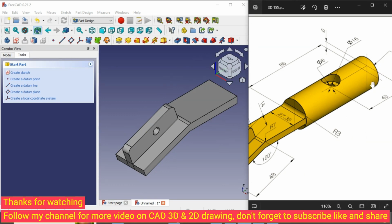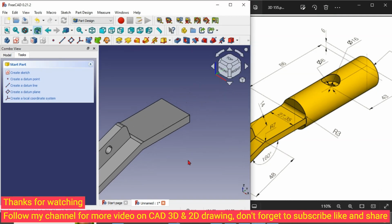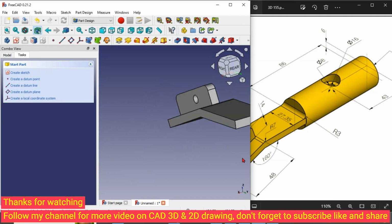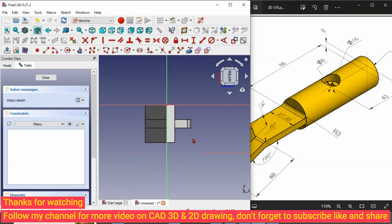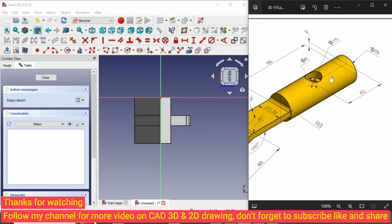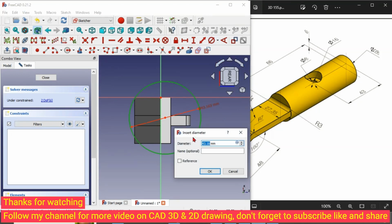So we need to create the cylinder, this cylinder here. We'll roll it a little bit because we want to draw on this side. So click at this side, click sketch. For this cylinder the diameter is 28. We draw a circle and set the diameter to be 28.